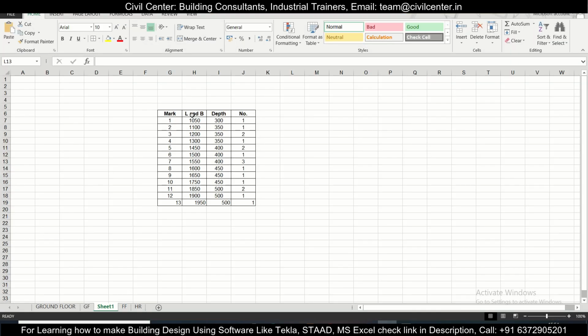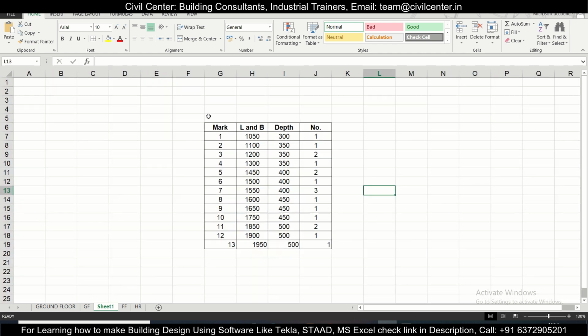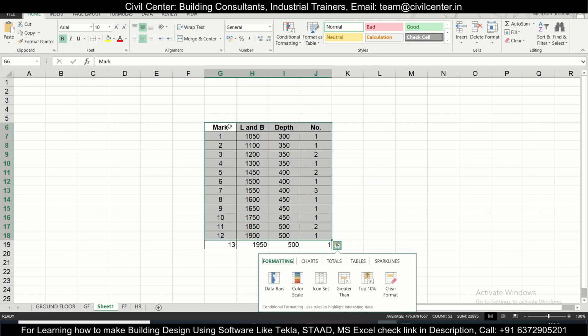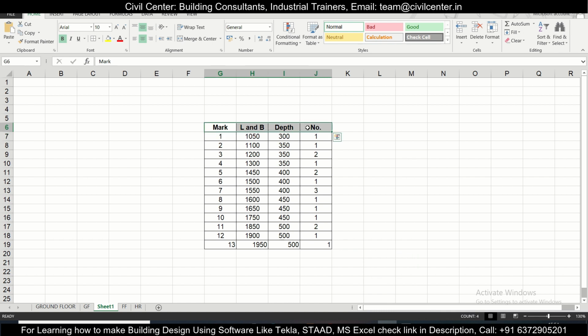So for grouping, we can't reduce the size, but we can increase the size of some footings. Let's say we'll put these 3 in a single group, so we'll give it a size of, let's say, we'll just copy this particular option here. This will be the final one.